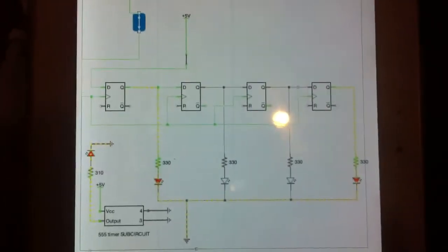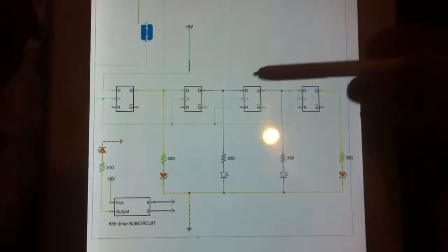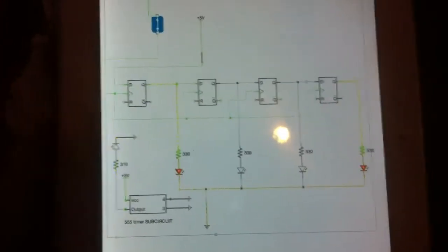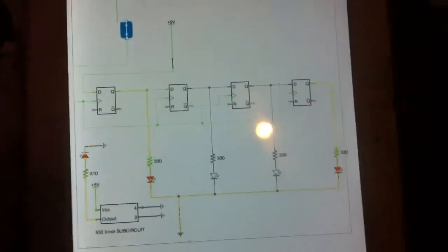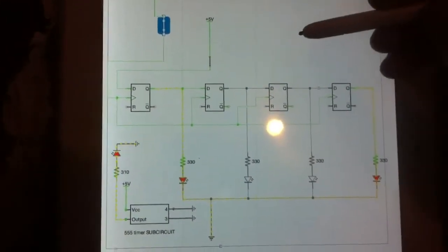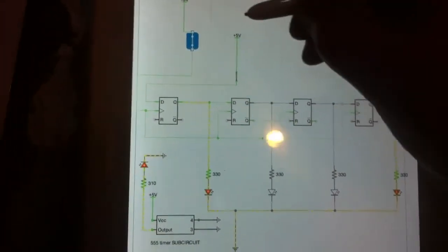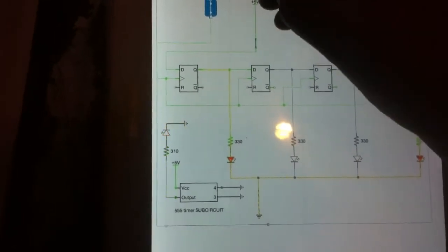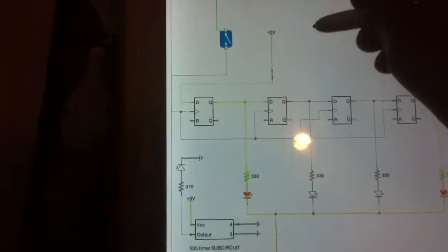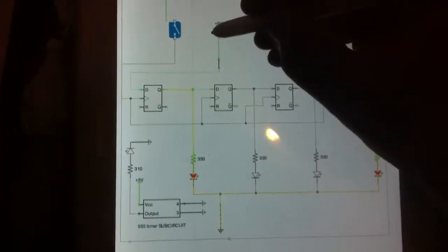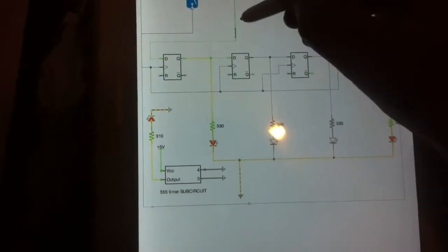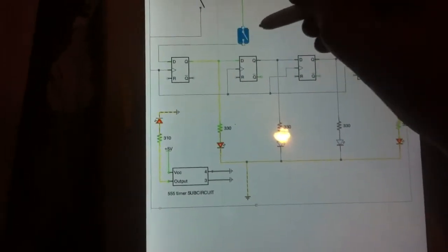So basically the function of the register is just to register the values we are going to enter, and it's going to shift them to the right. The way it works is that we have to register a number when the clock is in 0. So in this case we are going to register a 0.